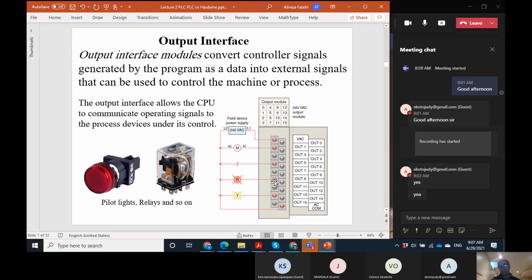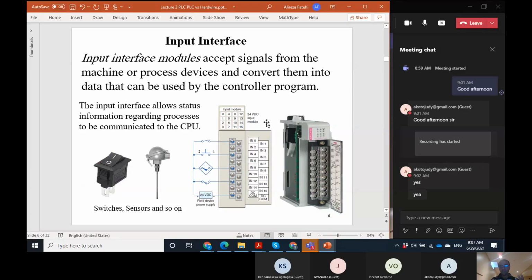to the output modules. But these terminals in the input and output modules, in fact, the PLC input-output card, let's say input card, reads the voltage on this terminal, the voltage changes according to the state of the switch. So something that changes at the terminal of the input cards is the voltage, just signal, or maybe current.